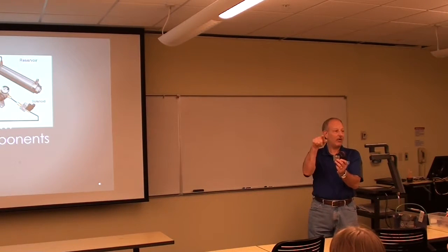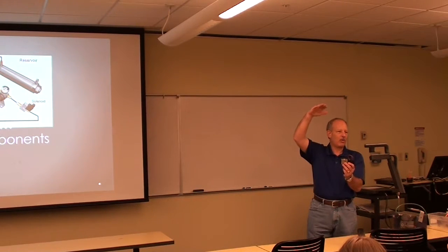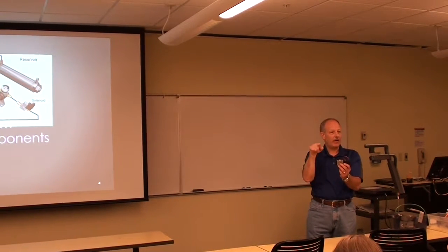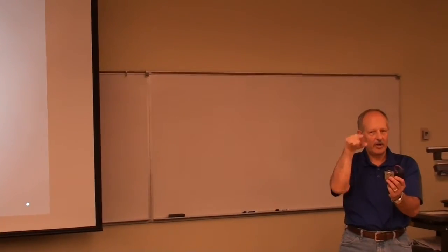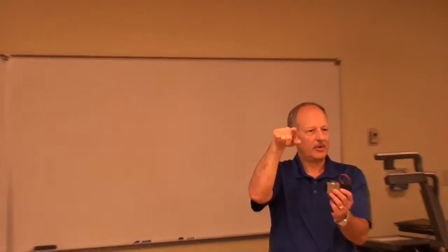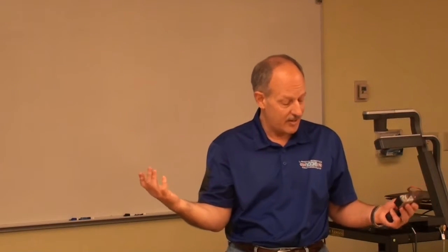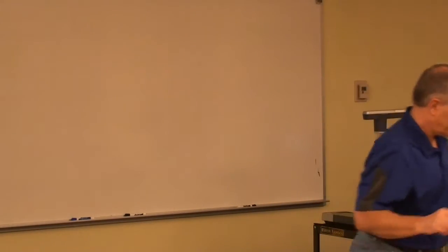So now if I have a pin, and this is what 1038 did last year, they used the motor to pull the robot up, but then they had a cylinder that went inside the lifting mechanism, and right before the end of the match it would extend and lock, and it didn't matter what the solenoid valve did, it would hold the robot, okay? Because the air pressure does go away, right? Does the air pressure go away when you de-energize the robot? No. So that's something that's very useful.